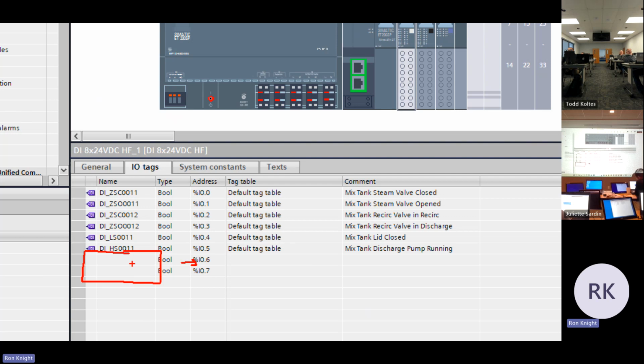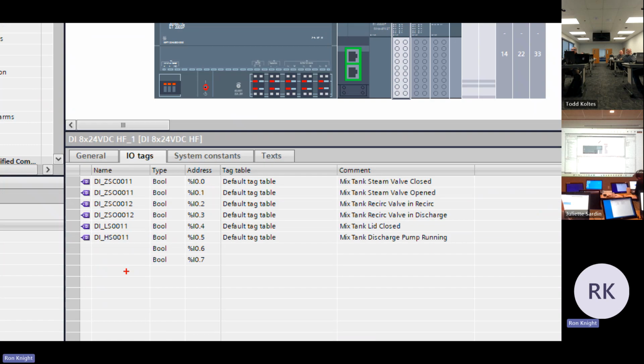I'm going to go ahead and do that for you. And it would be tag _1. Horrible name. But the software enforces that. So the fact that there is no tag here tells me that this guy is spare. He's not being used anywhere in the logic. I don't have to go and do a search or a cross-reference. I know from right here, not being used.